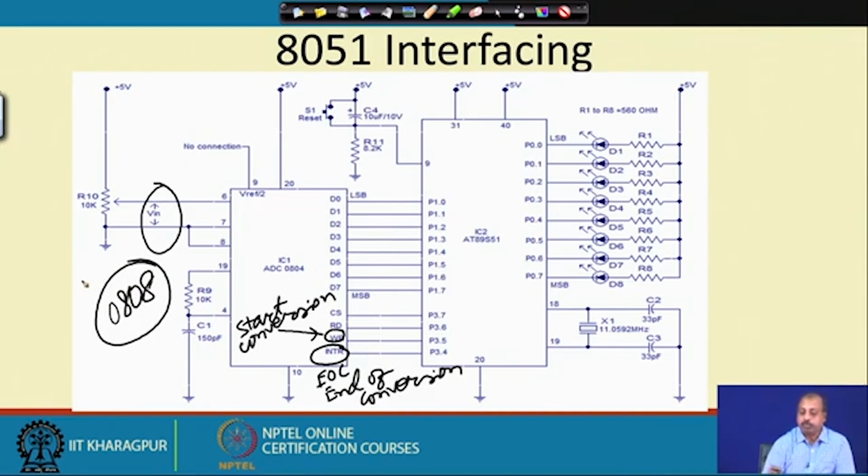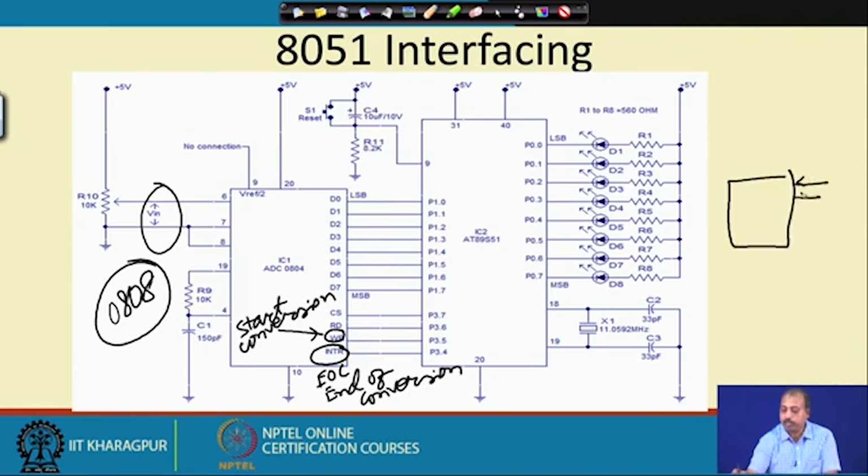Instead of a single analog channel, it can have a number of them, say 4 analog channels named AN1 to AN4. Some select lines will also be required from the microcontroller. By setting these select lines you tell which analog channel you are going to convert, and accordingly the conversion will be done and the converted value will be available on the data bus.